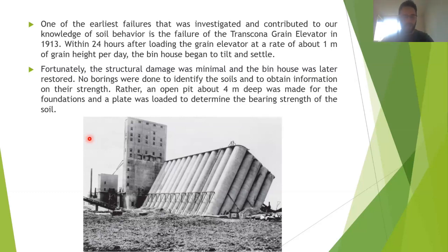So that's some stuff you need to understand first before deciding where you're going to take soil samples, and also you're going to take soil samples just before the foundations, in case you're not going to have a deep construction pit.